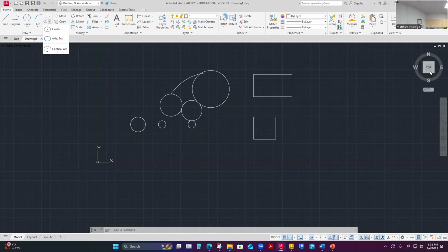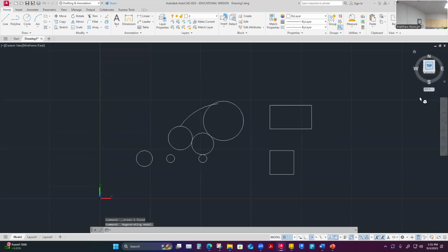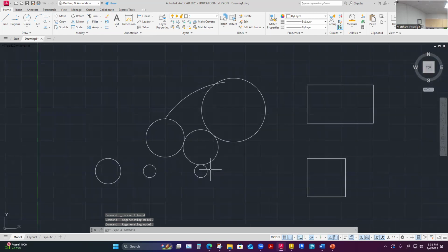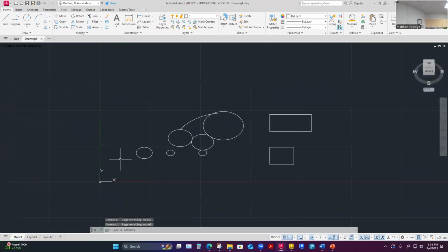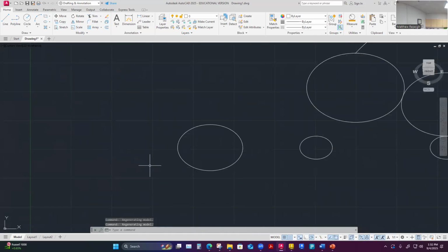I don't know if I can replicate that on here with the circles that I have. Yeah, I will. So here's my tutorial on what an ellipse is. Here, I'm in 2D space, and I've drawn my circles all over this place. Let's take a look at this first circle I drew. An ellipse is what is formed when I'm looking at a circle at a slightly different projection angle, like my viewing plane changes from being direct on. I can do that by rotating my navigation. I haven't changed the geometry of that circle. All I've changed is I'm viewing it slightly differently. The circle becomes an ellipse.